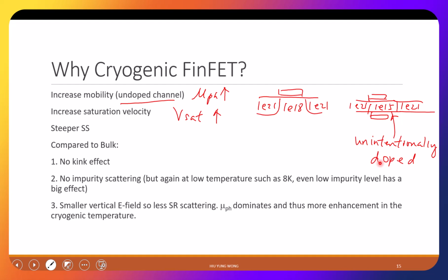So in that old case, that 1E18 is just coming from your bulk wafer. No. We do channel implant. Okay, when I say 1E18, I'm mostly talking about the region here. But your wafer is very deep. Your wafer usually starts with 1E15 or 1E16. So you need to do channel implant to adjust the threshold voltage. You get 1E18 by channel implant. Okay, and that's how you get different threshold voltages on the wafer, high voltage, low voltage, because they all have different substrate doping. And you will see that if you try to fit all the curves.